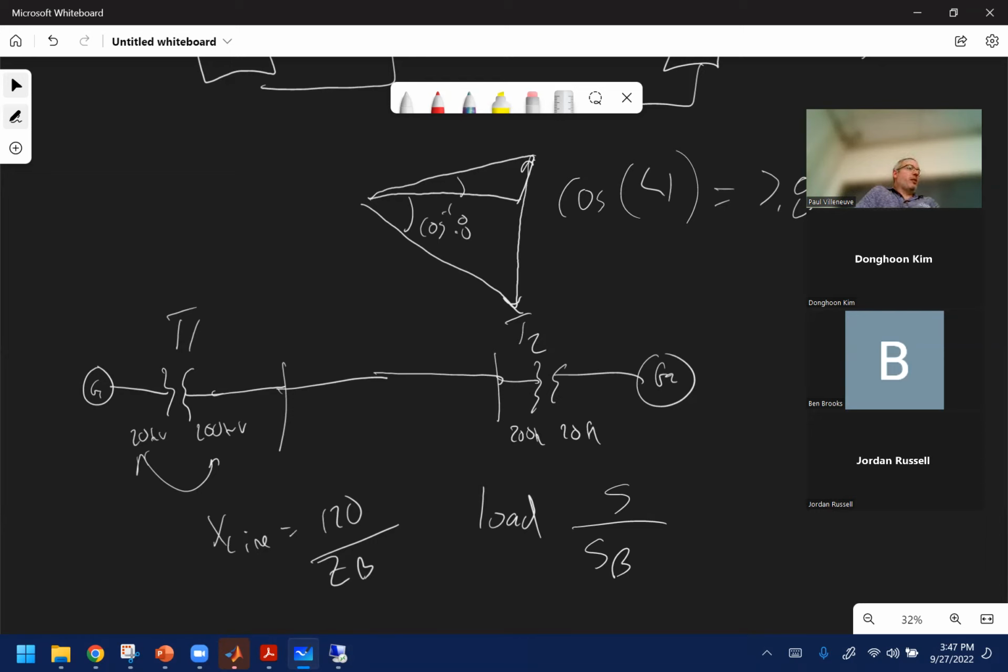The 48 megawatts plus 64 megavar. Well, the S is in the positive direction. So when you go S equals VI conjugate, you have to take the negative of the angle. So that would be a lagging power factor. But you would still draw it as 0.48 plus j0.64. You still have a positive. It's only that the current lags.